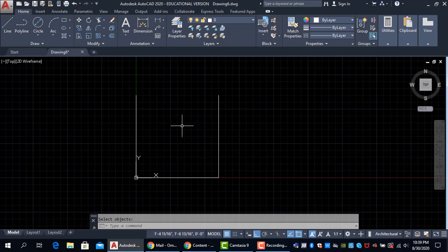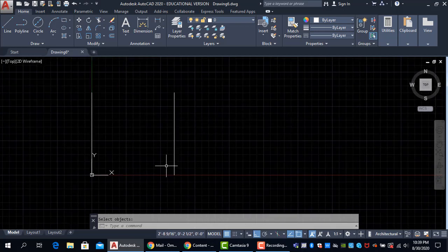Okay. Once the command ends, you can see the cursor going back to crosshair. Okay, so I'm gonna do it one more time. I'm gonna grab the erase tool. Notice that it changes to the big box, and I can select what I don't want, and I can delete. It's not just with erase, it's with different commands, but we're gonna learn them as we go. So I just wanted to show that in case you see me erasing stuff and you see how it changes.